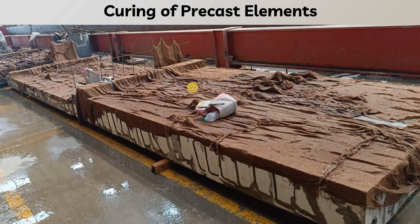If we talk about the curing of the panel, the curing can be done manually, as well as steam curing can also be done. In this case, you can see this is the gunny bag that is used to cover the precast element, and here this is the nib portion that we have already discussed.